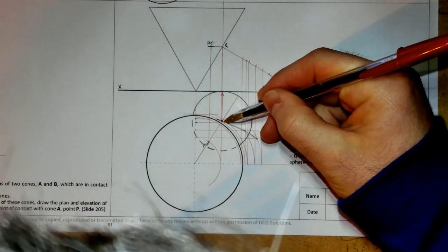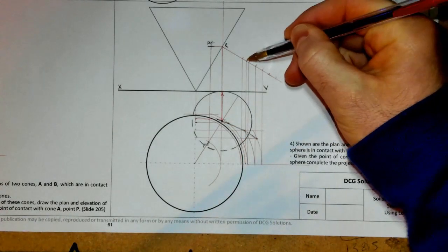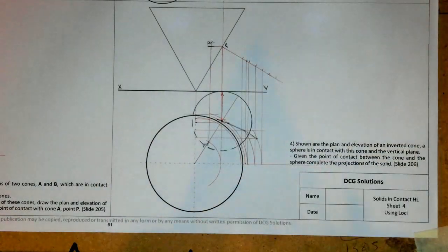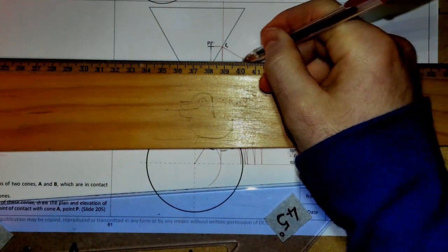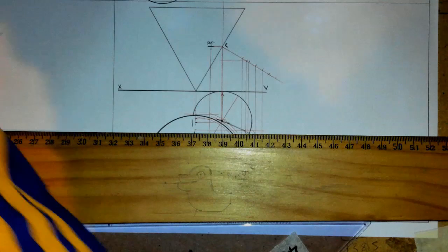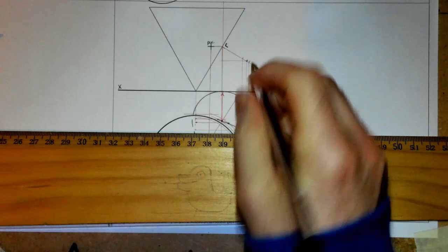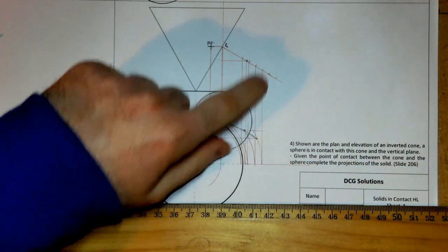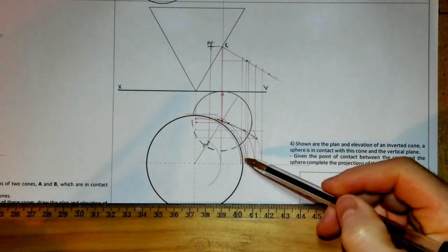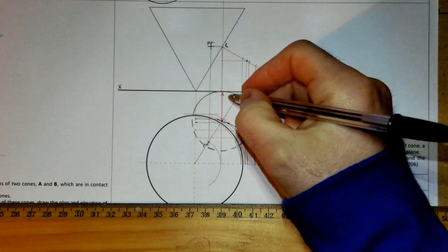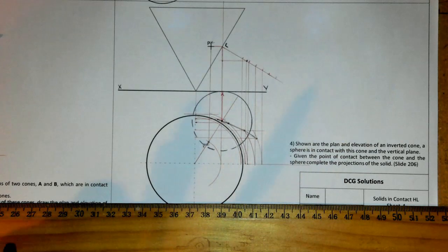So when I rotate it around back to the extreme generator, it would come down here, and it would have been right here. It's actually bang on the 18. So that's the height of the center there, as it rotates around. So technically, my new center, once I bring that one over, was the height of the center when it was rotated around, and my ghost sphere, we found it over here, and what we want to do is rotate it until it's in its correct position. So when that's rotated in its correct position, it's right here. Take the exact same radius as I had in my plan.